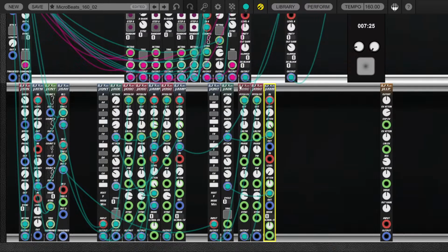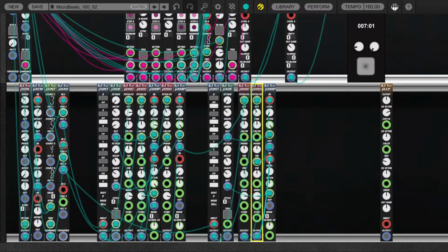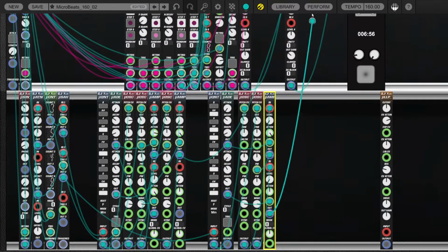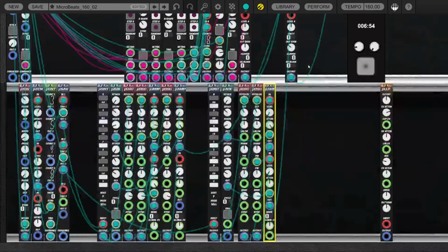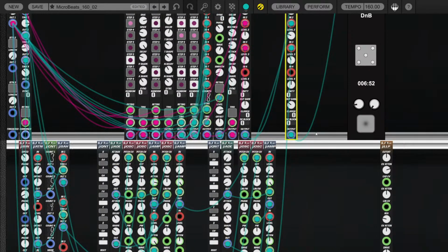And now the first oscillator, this will be an FM patch again, will be our modulator, and the second will be the carrier. So by feeding the modulator oscillator through the amplifier, we have control over the strength of the modulation. Let's use phase modulation this time, so patch it into the PM input, and our carrier goes out into the second channel of the amplifier and into another channel in the mixer. Let's turn it down a little.